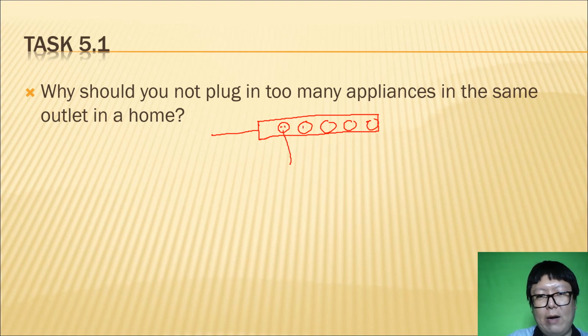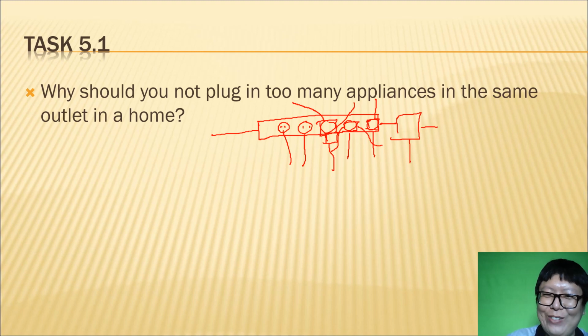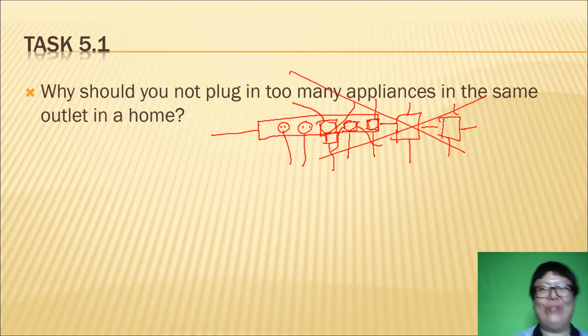You put a branch plug with 3 sockets, then another with 3, and another with 3, and after that you put again, and this is not allowed. Find the reason why. This is not safe, and dangerous for the electric installation in our house.